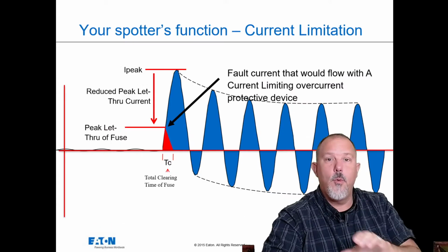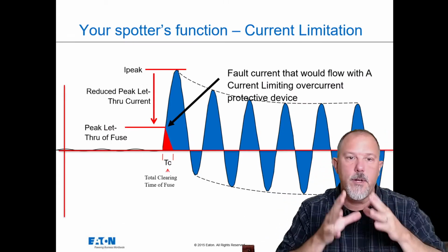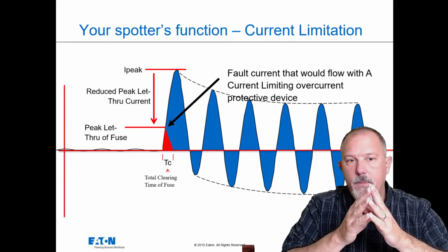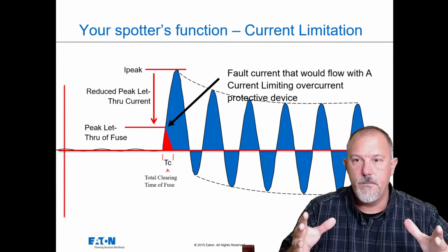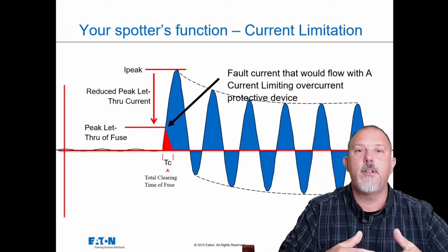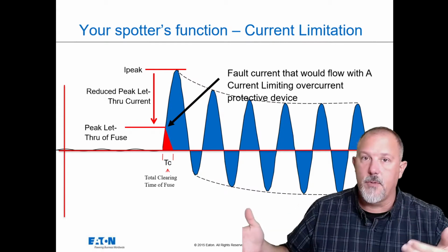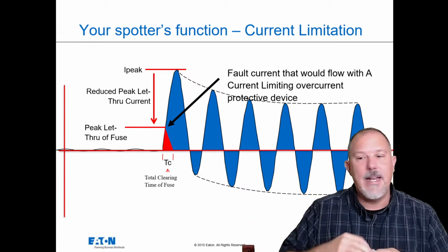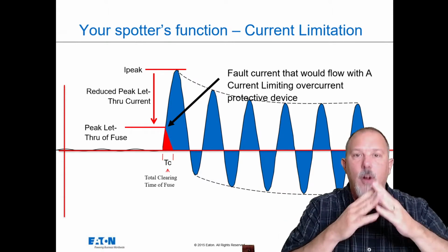So when you think about what's happening during a short circuit, you have a fault current that's flowing, and when we calculate fault current, we're calculating an RMS value, meaning it's going to persist. We don't calculate the peak. We don't calculate an average. We calculate an RMS current.